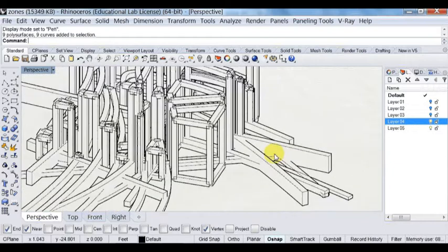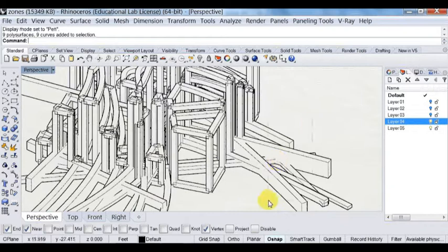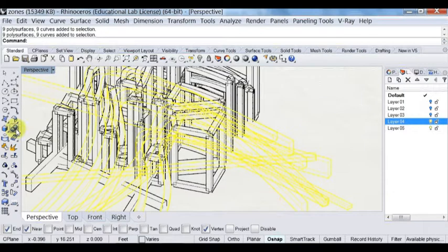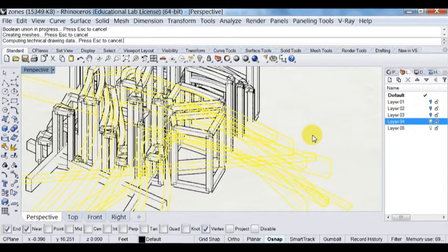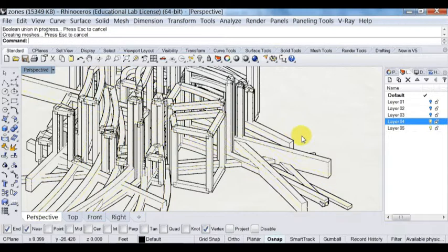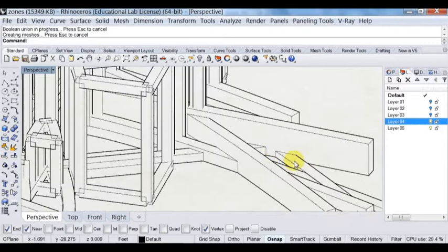So if you do want to show the intersection line, you have to manually unite them together, pulling and uniting. It should be easy to compute if it's just simple lines. And then as a result, you should be able to see all the individual lines in between. See that? Okay, so that's a Boolean operation. You could do that in Grasshopper too.